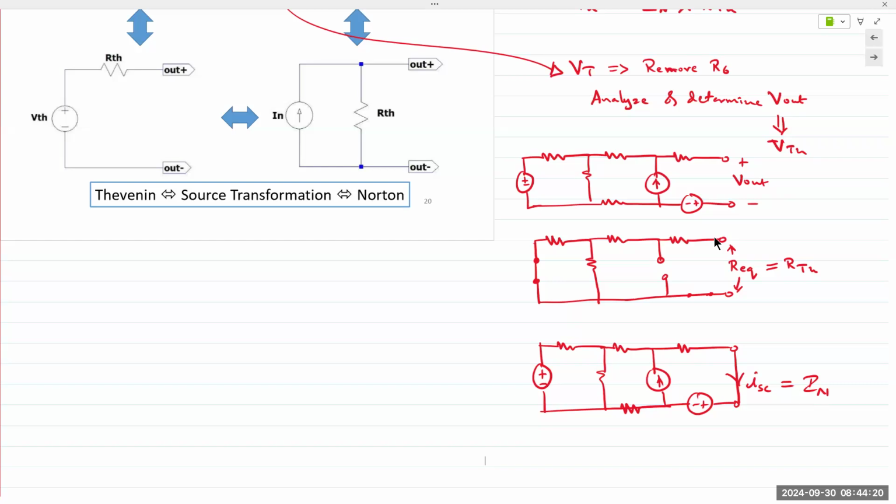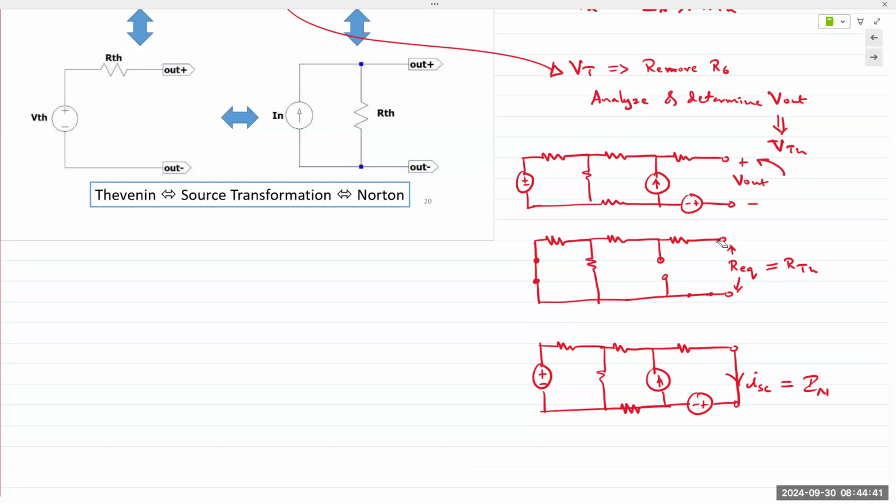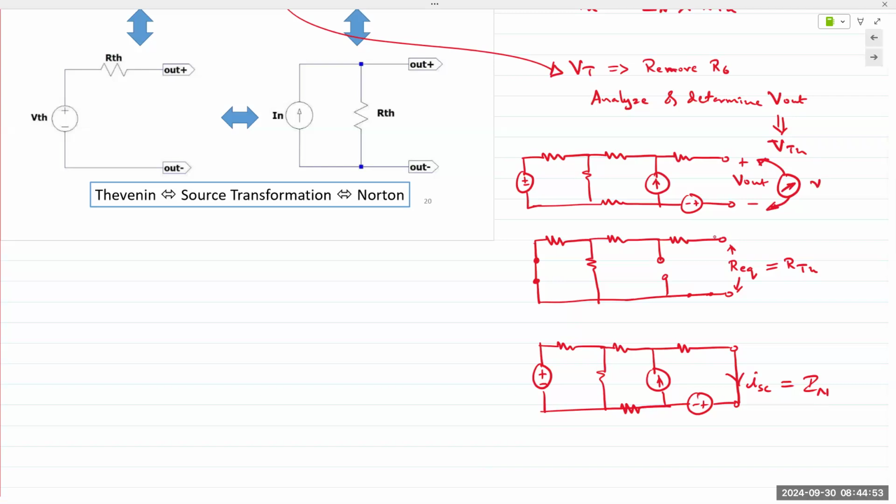Okay, so, but anyway, so Thevenin voltage measurement, all 3 quantities to measure in the lab takes literally less than 2 minutes, not even 2 minutes. Your circuit's done correctly. You have your 2 measurement terminals. You take your multimeter, you connect it at the output terminals right here. It's a meter. So you connect it here, put it in voltage mode, measures the voltage.